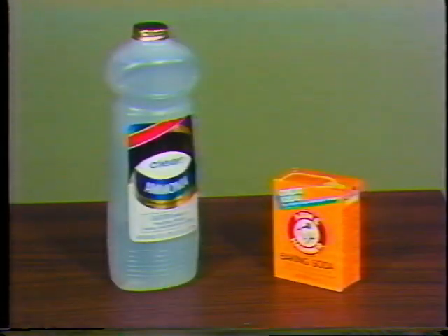But you should know what to do in case they don't. Make sure you know where the closest eye wash station and shower are before you enter a battery room. If you get acid in your eyes or on your skin, the first thing to do is wash the area with large amounts of water. Then get help. If you get acid on your clothes, it'll probably cause holes, but you can minimize the damage by neutralizing the acid. Use dilute ammonia or a solution of baking soda and water.